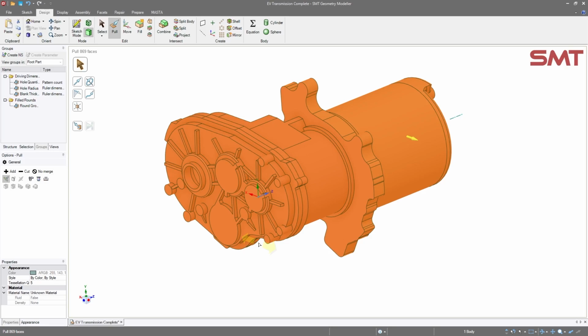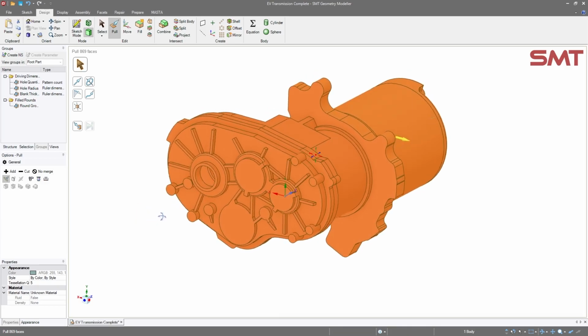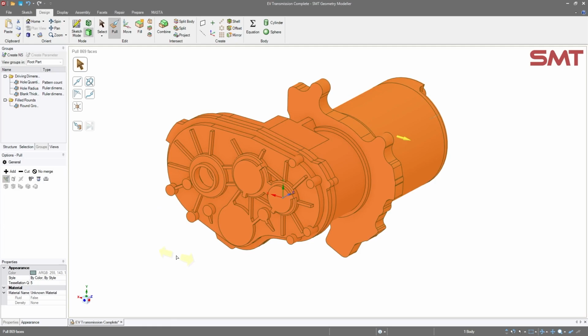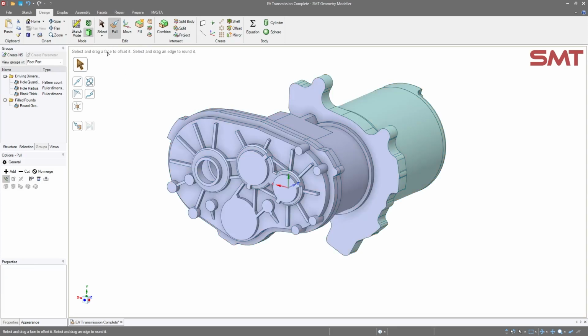Another option, if you want just a quick-fire initial solution, is to actually generate the facets inside Geometry Modeler itself and to use a tool called shrink wrap to simplify that model, because it's the detail on the models a lot of the times that will cause those problems. Now this functionality is still being applied to the link between Geometry Modeler and MASTA, so the actual button to send it over is not there quite yet, but I'll show what the functionality is going to do.